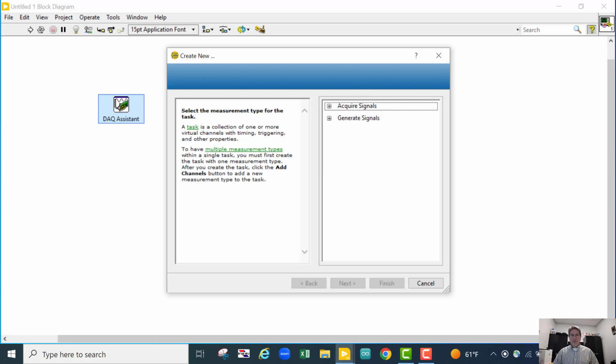So we can write a LabView program that generates signals between 0 and 10 volts. We could turn a knob in LabView, that would cause an output module on the DAQ to output voltage, it would go into the wind tunnel and make the speed change. In fact, you all are going to use that on your pitot tube lab.